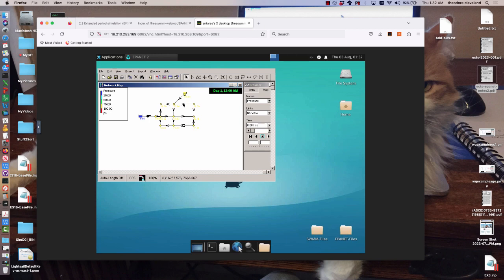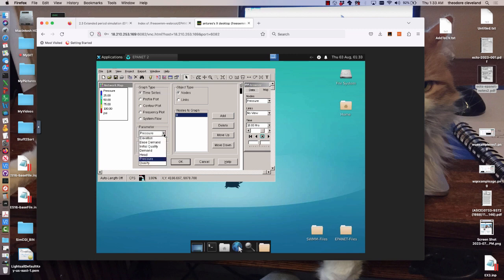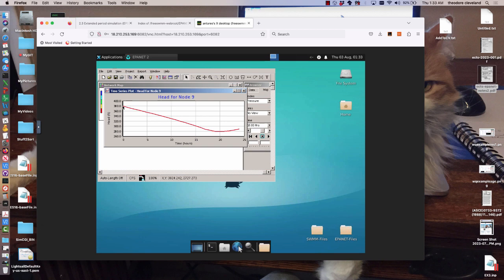Successful run. So by making this pipe and that pipe bigger, and I made the tank considerably bigger and considerably taller, we were able to complete the run, and we still get pressures below 25, but we don't go negative. And if we look at the tank head, which is proportional to the level, the tank drains, and starts to fill.